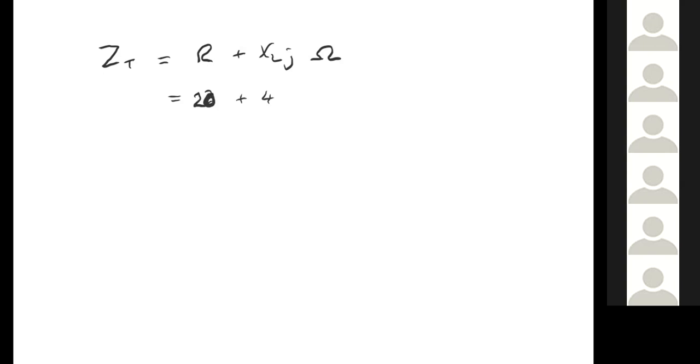And inductive reactance, just remind me what that was because that's on the other page. 15, wasn't it? 15 ohms, yeah. So 20 plus 15j ohms, and we could just do a straight convert to polar on that. For Z is equal to...